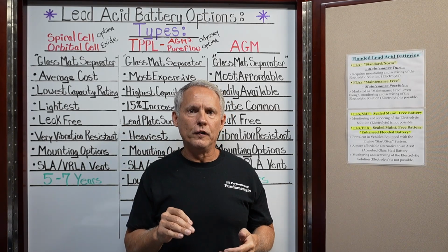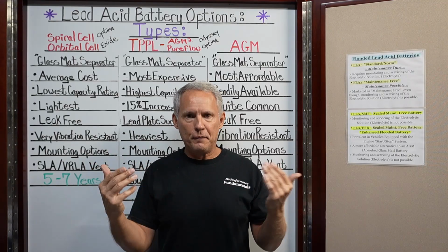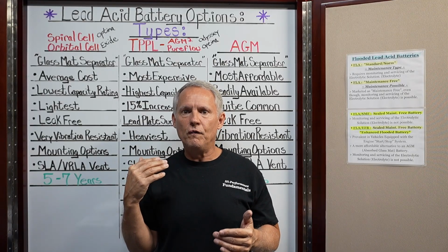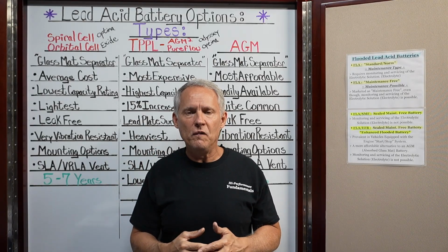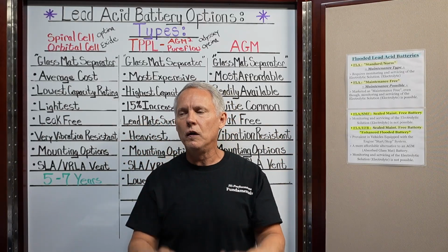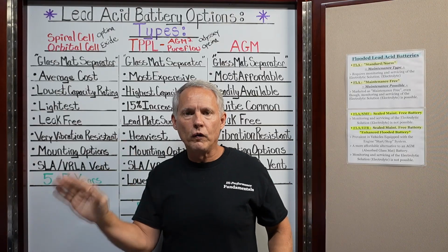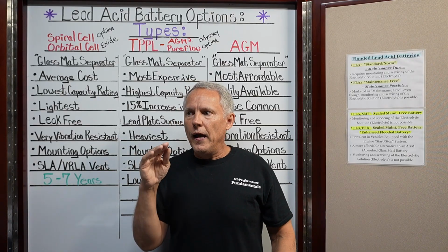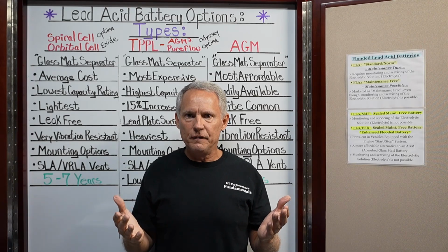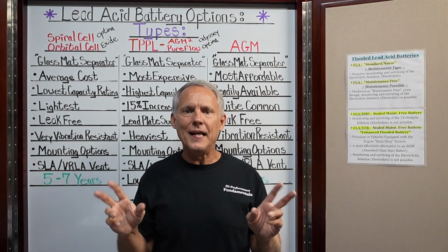They do make alternators, universal alternators usually, for performance applications where you can actually adjust the voltage regulator. So if you want it to put out 15.8 volts, let's say the battery manufacturer says we want 15.6 volts, or maybe a range, you can adjust it for that, okay? And then your alternator will put out the correct voltage. And at that point, really, there's not much of a negative to it. I can't say that there's going to be a big negative.